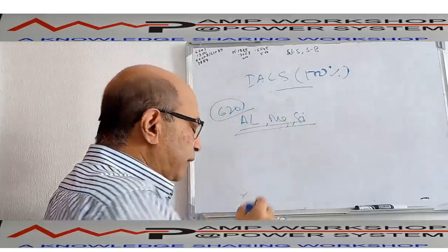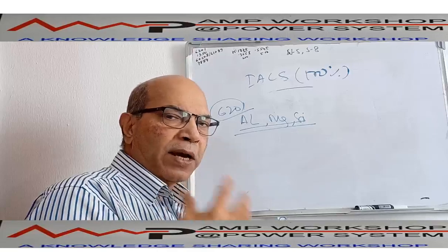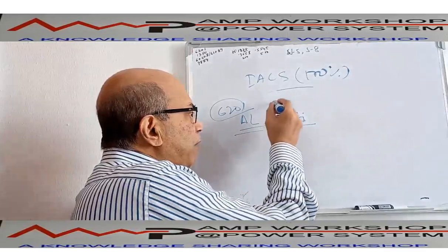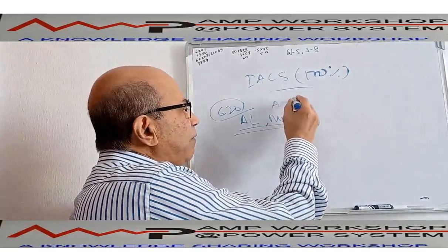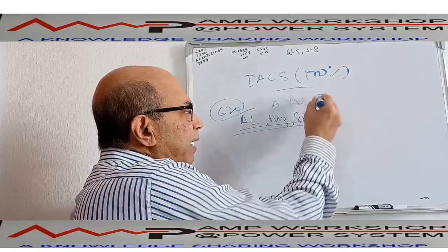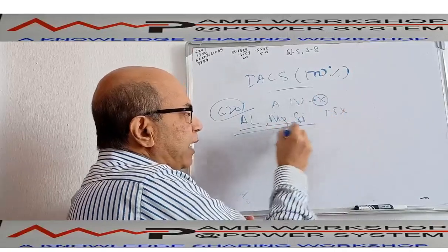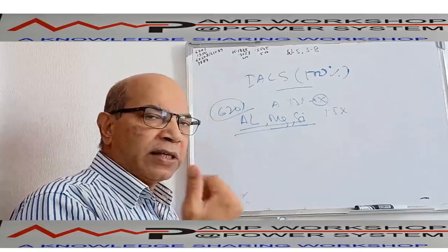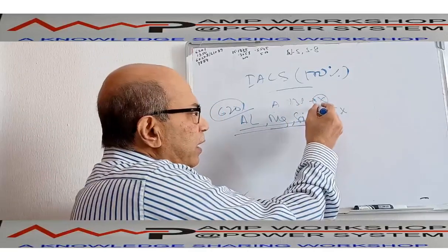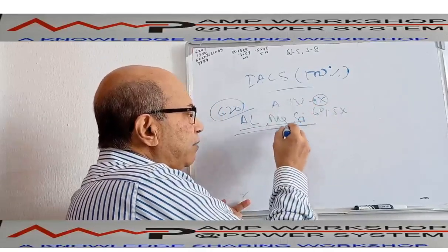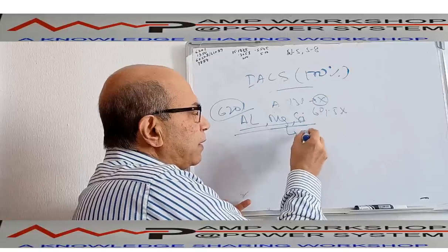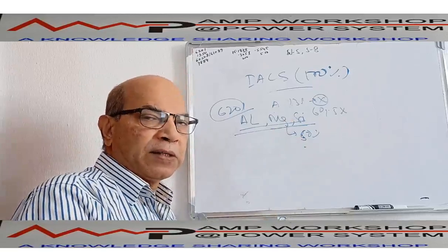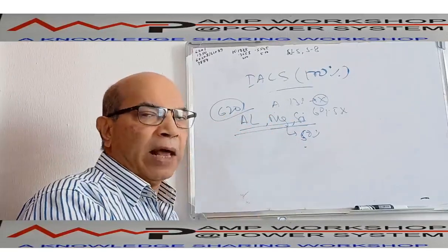By adding this magnesium and silicon, what has happened? The low mechanical strength of aluminium in comparison to copper can be improved by 50%. If pure aluminium, that is 1350, has mechanical strength X, the mechanical strength can be improved to 1.5X by adding magnesium and silicon. But by adding magnesium silicon, the conductivity is slightly reduced. Pure aluminium conductivity is 60%. When we add magnesium silicon, conductivity comes down to about 50%. So 10% conductivity is reduced, but the mechanical strength increases by 50%. That is one of the advantages of using aluminium alloy.